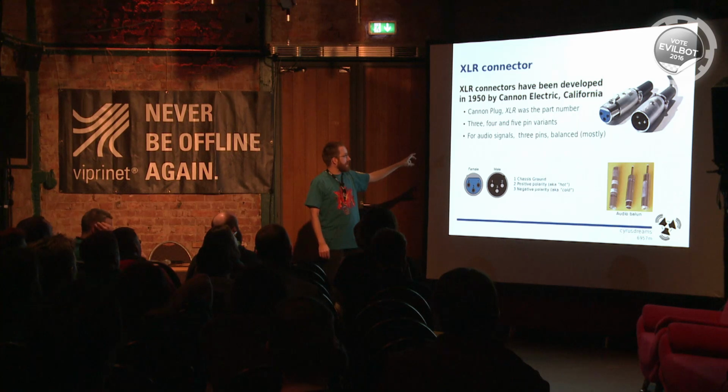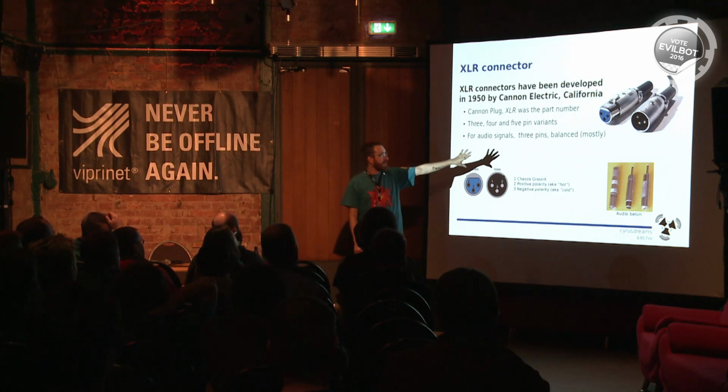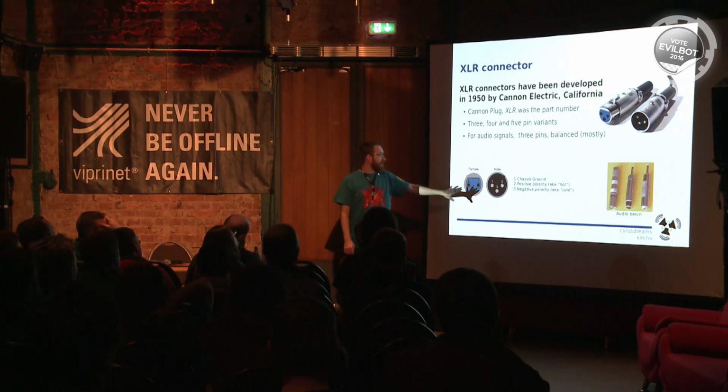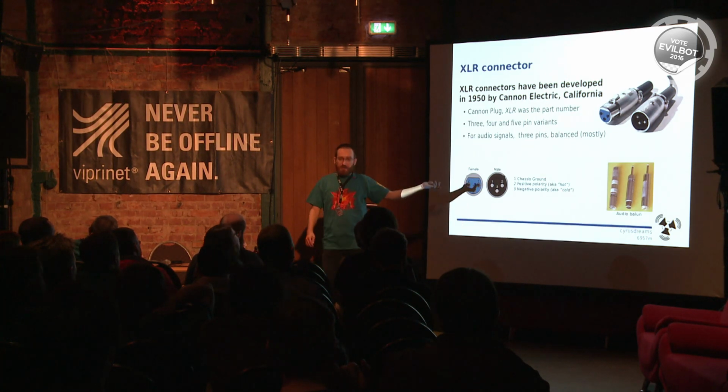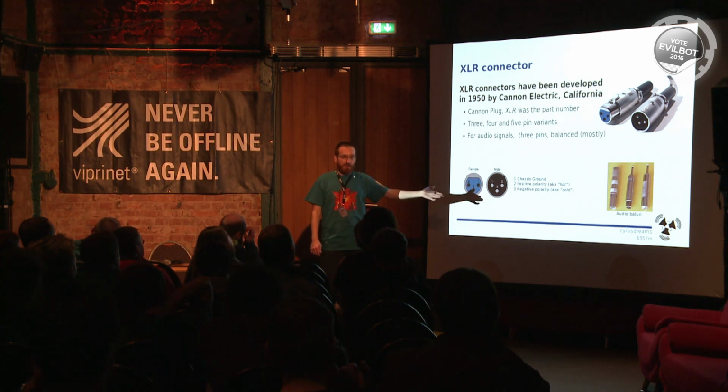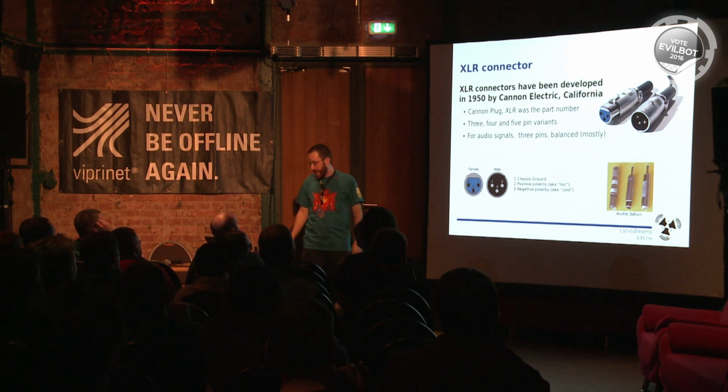And for audio signals, the 3-pin balanced one is normally used. You have the ground, and you have positive and negative polarity. Positive is sometimes called hot and negative is sometimes called cold, just to have the language.